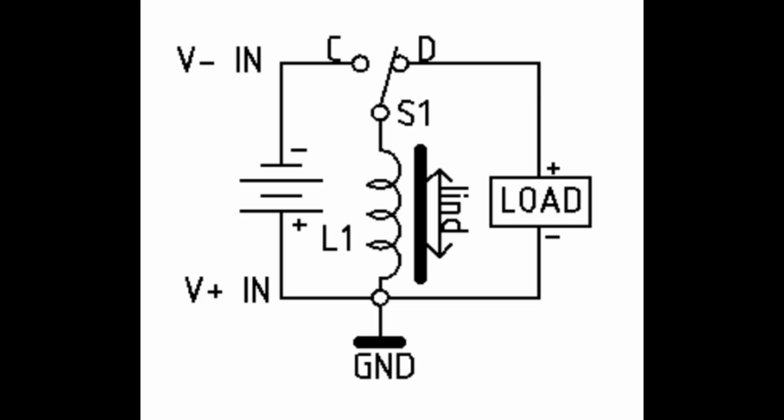Inductor energy equals 1/2 of the inductance times the peak current squared. If you repeat this cycle at a fixed rate, a fixed controlled power will be delivered to a load, because an energy delivery rate is power. What the load is does not matter. It could be resistive, like a heating element, or another power source, like another battery being charged. A delivery rate of 1 joule of energy per second gets you 1 watt of power.